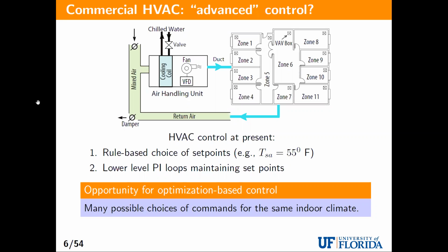Whereas the buildings are never in steady state: outside temperature is changing, and the load inside the building is changing because people are moving in and out. Because of that, this is not the best decision at all times. This is the best decision at certain times, but not at all times. So what you really want to do is online optimization based on the current situation.